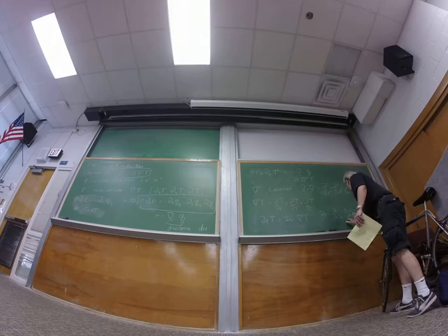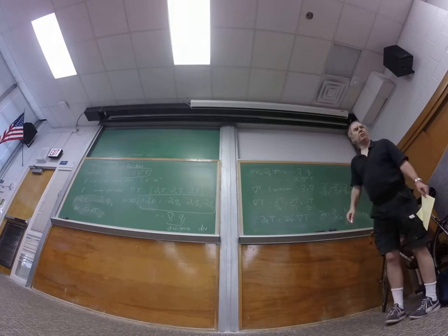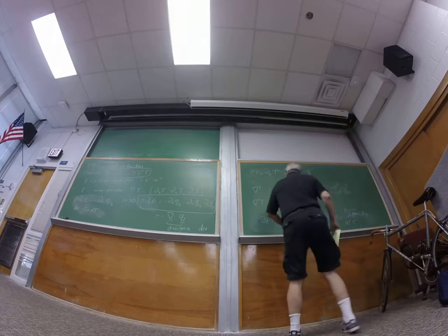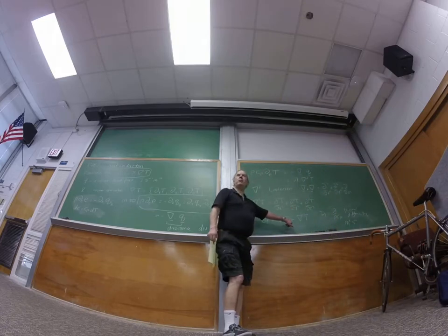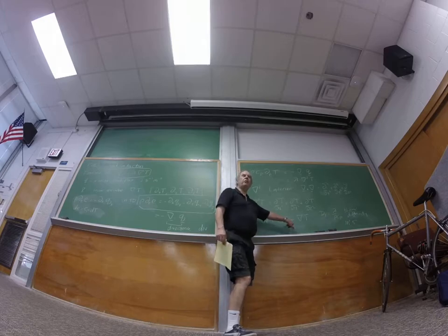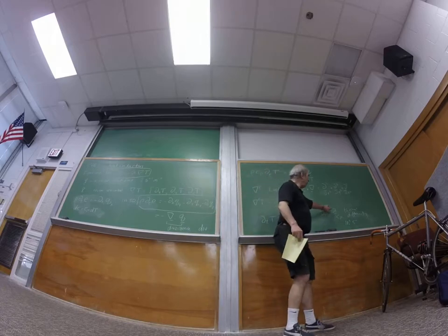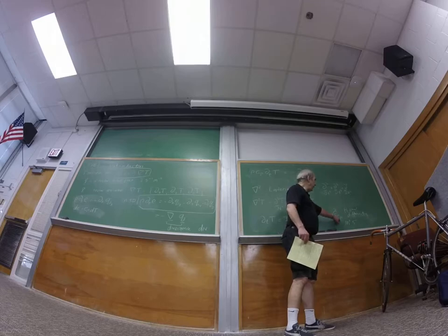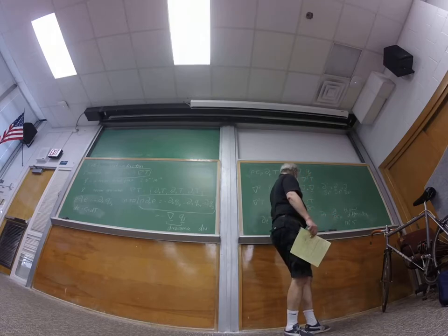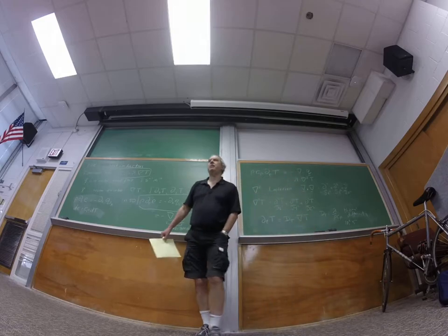So it has the units of a diffusion coefficient. It's just meters squared per second. Okay? So basically any particular material, whether it's solid or liquid, it'll have a thermal diffusivity, and you can usually either look up the thermal diffusivity itself, or you can look up the thermal conductivity and the heat capacity and the mass density and calculate it. But usually you can find thermal diffusivity directly.